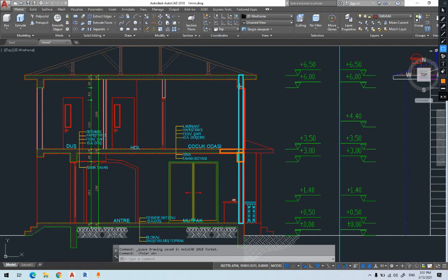We will discuss this later. For example, later we'll put the beam here, and the slab basically. So this will be the slab. So the column will be replaced by them. This is totally fine in Revit. So you don't need to think, okay, this is the start of the column till here. No, you can just simply place it from the bottom till the top.